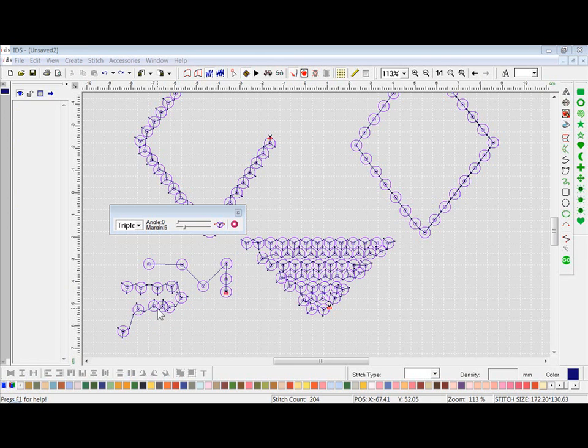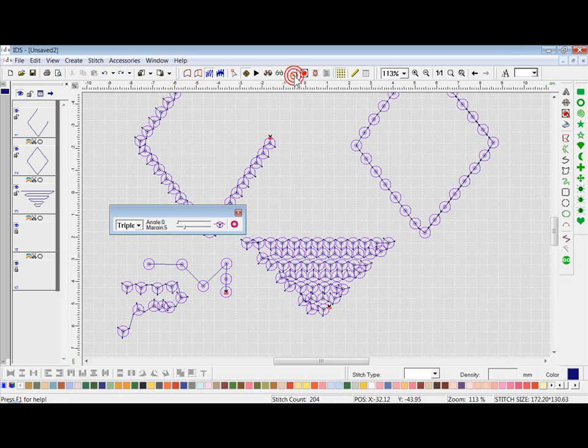Now on this area, since we do need to change the way the sequins are laying next to each other because of the overlapping of stitching on top of the sequins, we would actually go to our stitch editor, in the sense that we need to alter the individual stitch points. So while we're in stitch view, I am viewing my stitch penetrations with the stitch penetration on right now, and then also we need to activate edit mode, so we'll just left click on edit mode. When I do that, I can move my cursor inside the middle of the sequin.